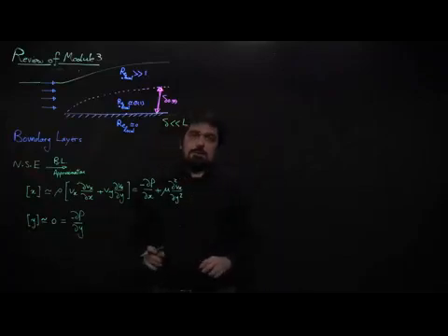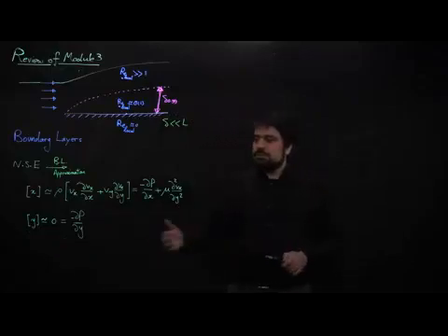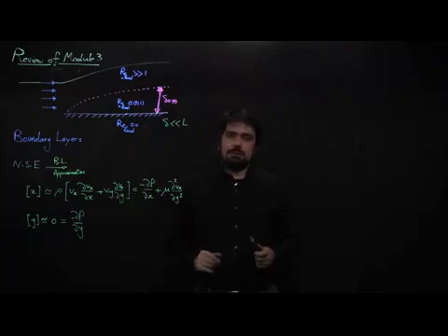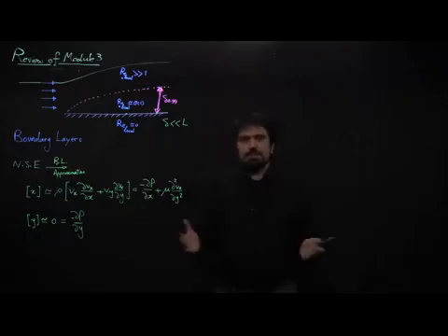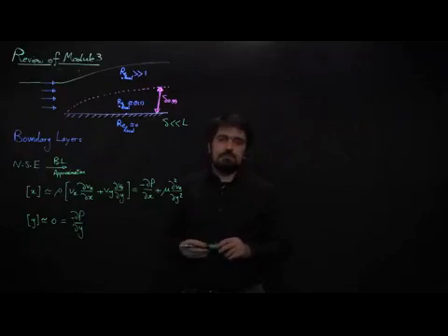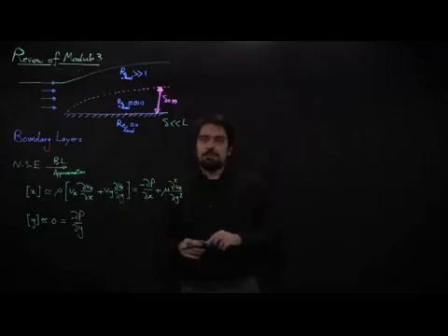The y component of Navier-Stokes can similarly be simplified, and we notice that it only tells us that the pressure gradient normal to the plate inside the boundary layer is negligible. This is when we neglect variations due to hydrostatics. But if we want to keep them, as we have shown before, you can always construct a modified pressure, P plus rho g y, and rewrite everything in terms of that modified pressure, and you will get exactly similar forms at the end of the day.